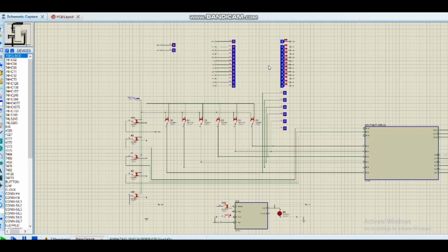For the third memory location, the address is 010, and the value we will be storing is 011 and 000. The first 011 says to output the value that was calculated, because we want to see that output. And the last 000 has no significant value, so we can give any value we want.